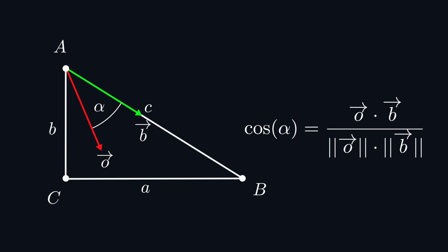By applying the arccosine function to the result, we get the angle alpha by which we need to turn the robot. In this particular case, we can tell the robot to rotate by an angle alpha and then move forward. But what if the robot's original orientation was O' instead of O? The angle between those vectors would still be the same, but in this situation, we would need to turn the robot by angle negative alpha instead of alpha.